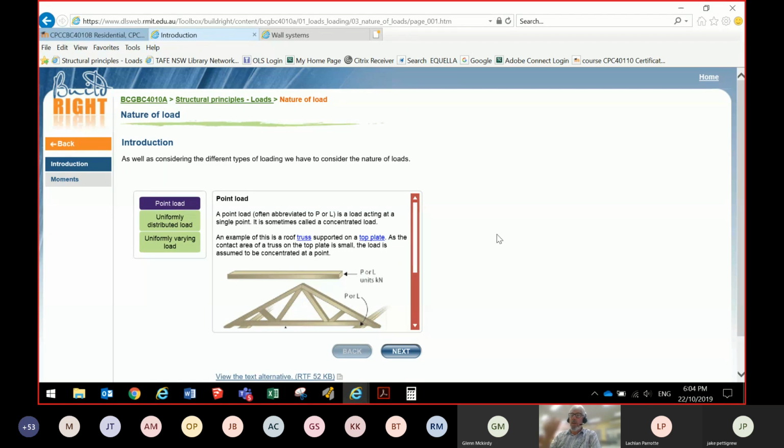So if you hook your trailer on, and then you have on that trailer more weight behind the wheels of the trailer, let's say it's a single wheel trailer, single axle trailer, then that trailer is going to swing around in the breeze all over the place as you start going fast down the road. And the faster you go, the more it'll swing. And you can see some good YouTube videos of how they demonstrate it. If you put the weight too far to the front on your tow ball, the same sort of thing will happen. Not as bad, but it can still happen. So the idea is to have the weight in equilibrium right in the center.